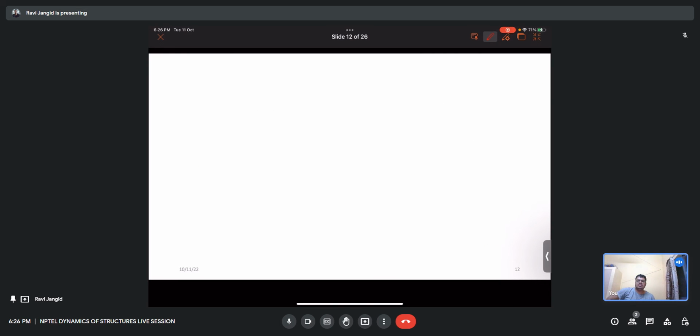Okay, so after getting D1, D2, D3, we also need the modal participation factor to calculate the modal response. Now we need to calculate the displacements u1, u2, u3 in each mode. From the previous question, the modal participation factors gamma 1, gamma 2 and gamma 3 are given here as we have calculated in question 1.